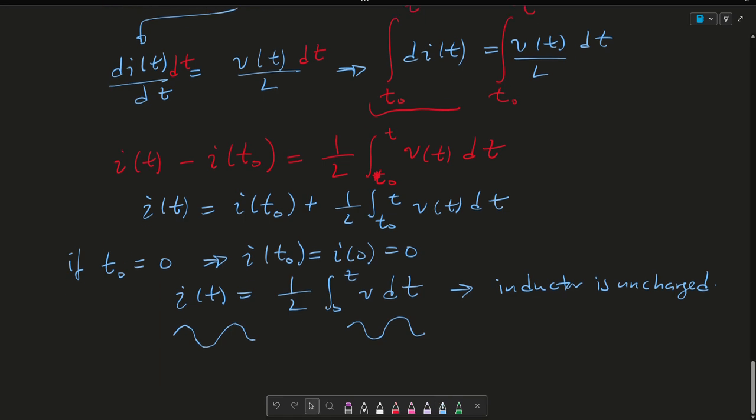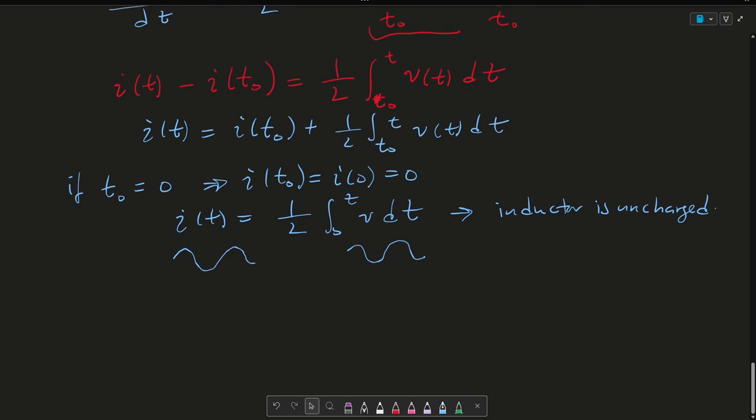All right. I don't want to dive too much into this, but power. So power, simply put, p(t) is vi, right? So this is L times i di over dt. So that's your power equation. If you get a positive power, this means that the inductor is charging up. And if you get a negative power, this means that the inductor is discharging, or delivering power to a circuit.